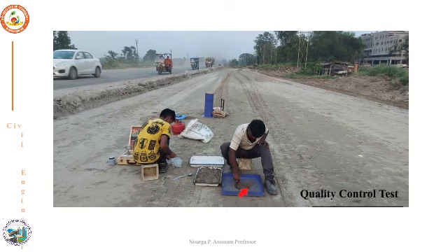At frequent intervals, as we mentioned earlier, if you are doing it for the embankment, for every 500 square meters of compacted area we need to take one measurement, and for the subgrade, for every 1000 square meters of area we have to take one measurement. And we have to take at least 5 to 10 sample measurements, and the mean value of it represents the field density obtained.